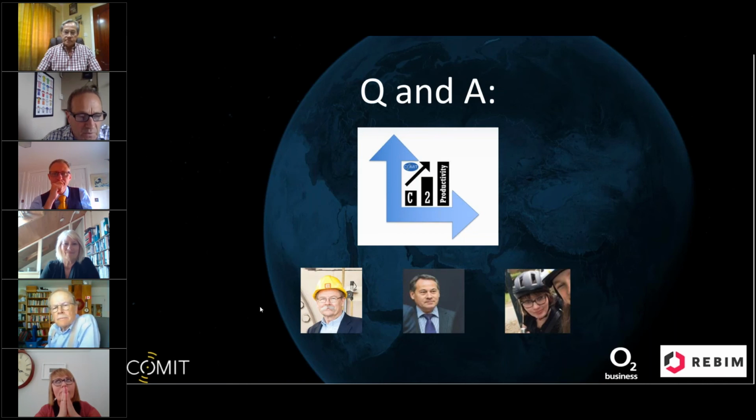We got a question from Andy Rhodes. Andy, thank you. There's a question, it's a statement. GPR also depends on the size of the pipe at the depth you're looking at, as GPR can see in the real world 5 times the size of the wavelength, which equals the depth of the pipe, but the pipe needs to be greater than 10% the size of the wavelength to be seen. Right, I think I've got my head around that, but yeah. Any thoughts on that, Russ?